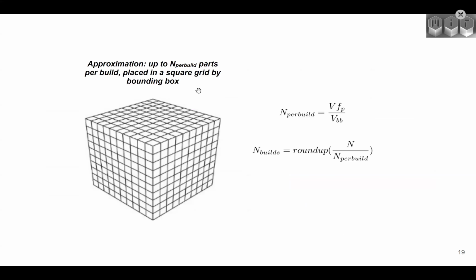And now we're going to get into the nitty gritty. The way the model works and the way that we think about calculating part cost is we try to simplify things a little bit. You can get really sophisticated and complicated with your costing. We're not going to do that here. We're going to treat every machine basically as a box. Then we're going to break that box up based on the bounding box volume of a part. If you don't know what a bounding box means, it means you take the maximum dimension in all three dimensions, and then we create a box around that.